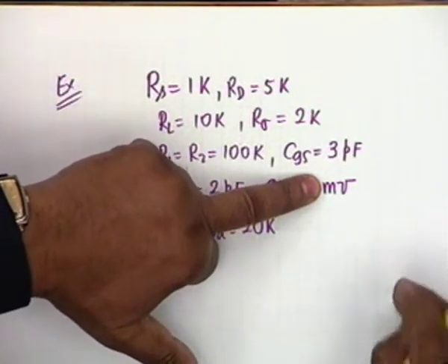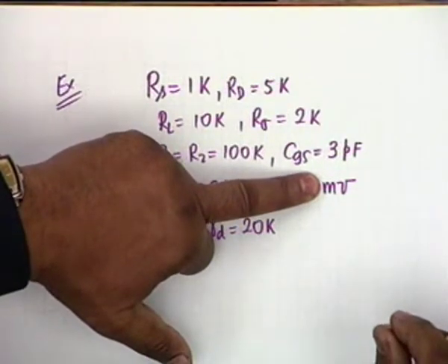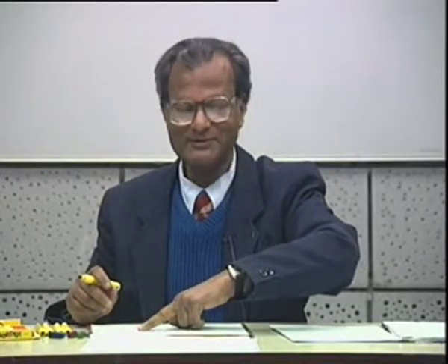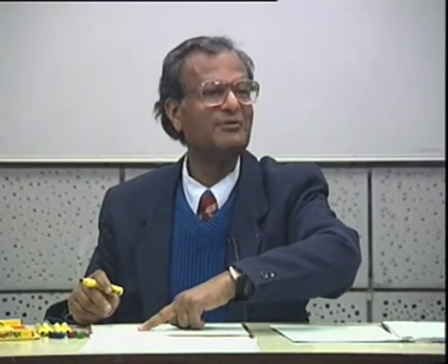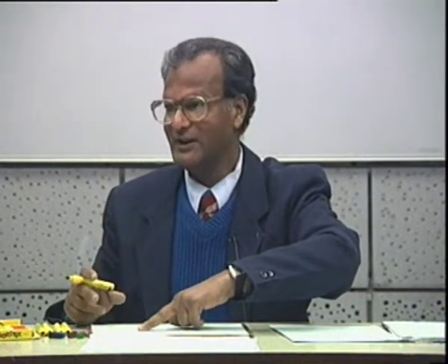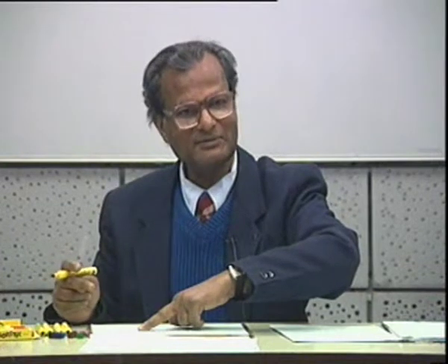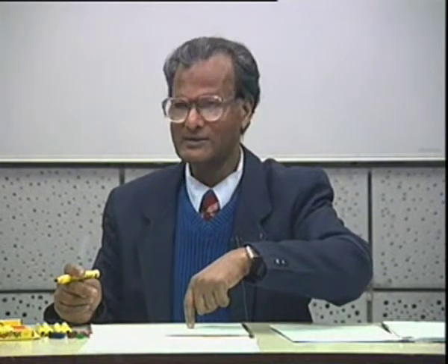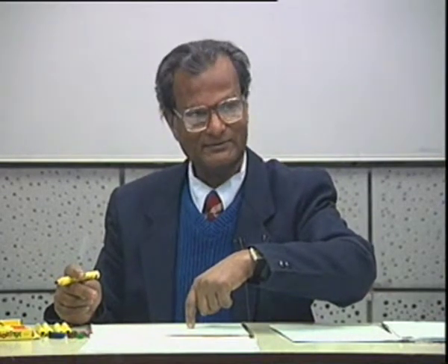VDD, why is VDD needed? To calculate VGS, come to the point. VDD is needed to calculate VG. Alright, not VGS, VG. VS will be calculated from ID times R sigma. So Vg minus Vs, that you have to substitute in the expression for ID and solve a quadratic. There you have to exercise your intelligence to reject one of the values. One value will be admissible, the other shall not be.